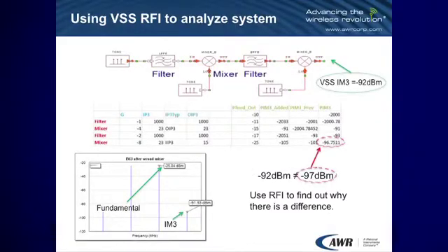In VSS, we have the intermodulation product as minus 92 dBm. The spreadsheet is calculating minus 97 dBm. We're just measuring the ratio of that tone to the third order intermodulation product. To get to minus 97 dBm, the previous value for the third order intermodulation product is minus 101, and we've added minus 105 dBm and got to minus 97 dBm. Okay, VSS is calculating minus 92 dBm.